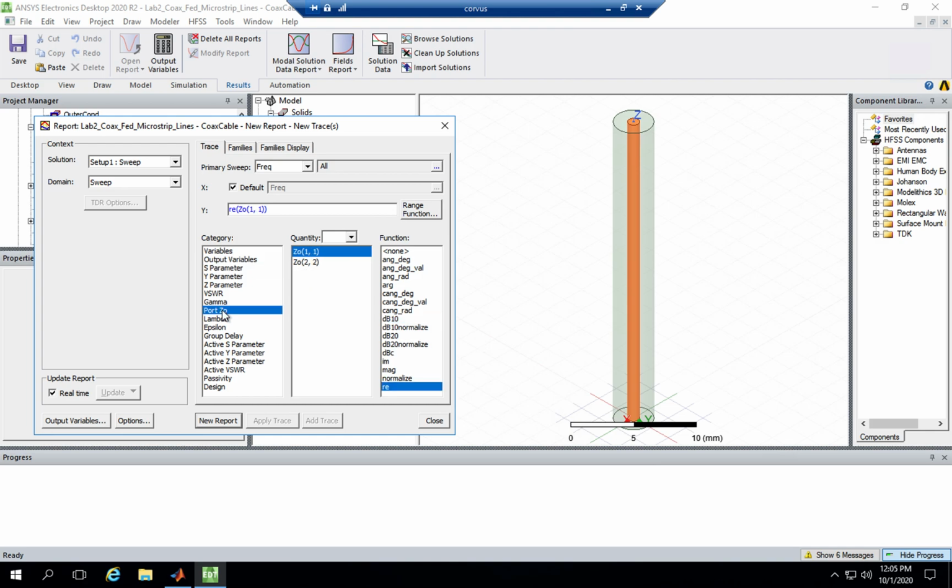we can plot the port Z0, which is the characteristic impedance of the line. And the reason why it would be of the line is because we selected the option to not renormalize the waveport. So we can look at the port Z0, and we want to check the real and imaginary. We can see what they look like.